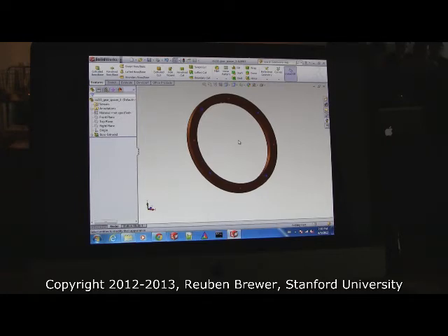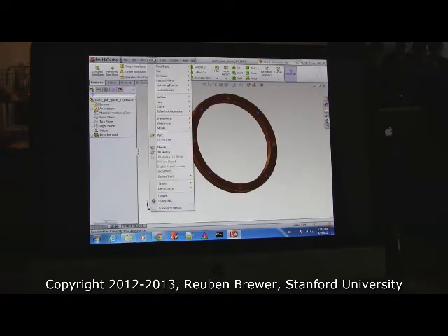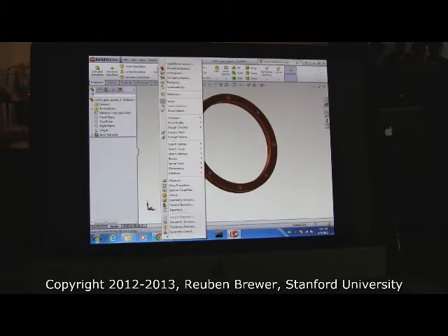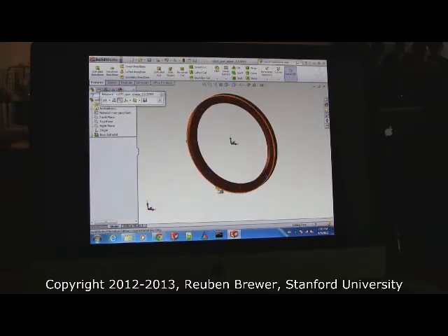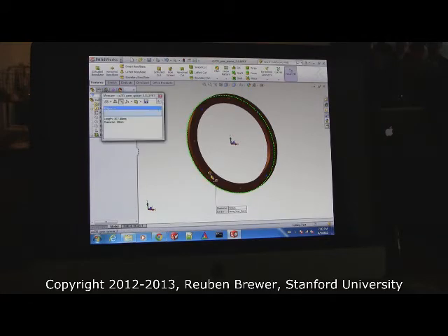Okay, now everybody pull up your measuring tool. That's Tools, Measure, and measure the outside diameter. Now, just look at my screen for a sec. For some reason, everywhere else selecting things is blue, but when you're with the measuring tool, it's bright green, just so you know.